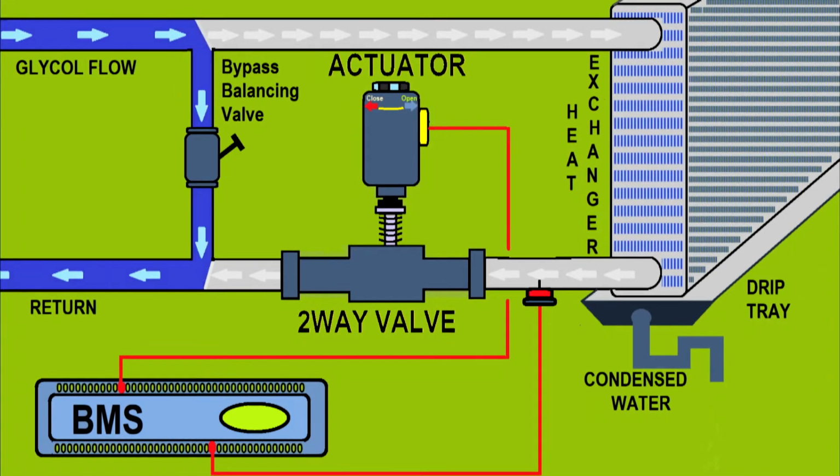In this example, you will see that the system is prepared to run on a cooling mode. Let's put it this way, it is summer, we run the chiller, we don't need the heating, so the pipe is cold, and again, this is just a branch of a larger installation. The actuator turned off the valve and restricts the glycol from passing to the heat exchanger, so the premises are already cool, and we do not need to cool the premises. So this is a cooling capacity control of the local area, but the chiller is keeping the glycol cold.